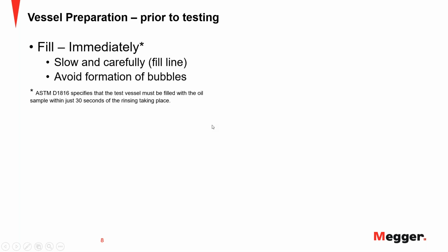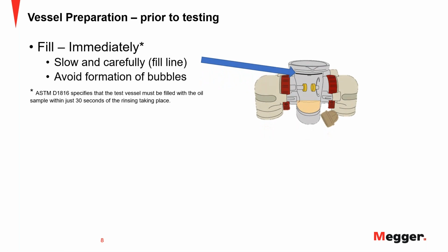And you need to make sure that you fill the vessel slowly and carefully. If you fill the oil too quickly into the vessel, you'll cause turbulence within the oil, and that can then generate bubbles. So you want to try and avoid the formation of bubbles.